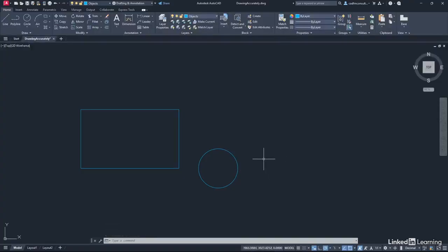Now we're going to utilize the center snap of the circle to generate 4 lines that look like this rectangle here. You'll remember the long edge of the rectangle was 5 squares, so that was 250 long. And the short edge of the rectangle was 3 squares, 150 long, because our squares were set to increments of 50 units. I'm not worried about what the units are. They could be millimeters, they could even be miles if you wanted them to be. We're just going to worry about the units and the distance that we're working with.